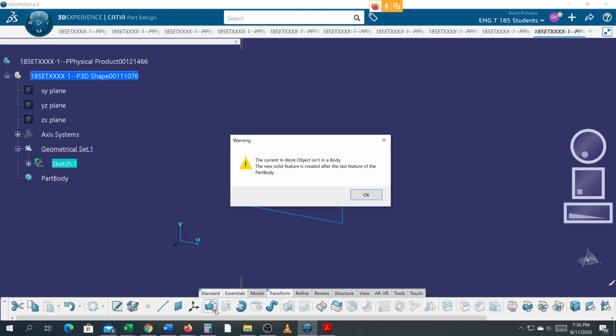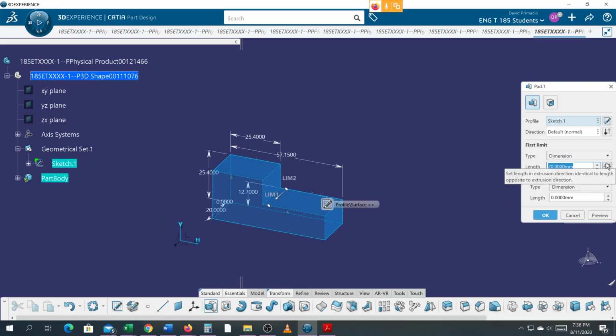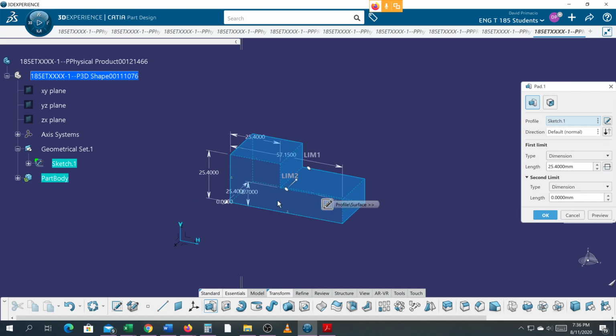Build a pad. Reverse the direction. Well, I'm in metric here. What you can do is go to space IN and it will calculate the metric. Okay. Actually, I think that part's a little bit thinner. Maybe I'll just do 1 IN and it'll calculate that to 25.4 millimeters. Reverse the direction so the numbers are in the front. This is the front view right here, that side. Select OK.